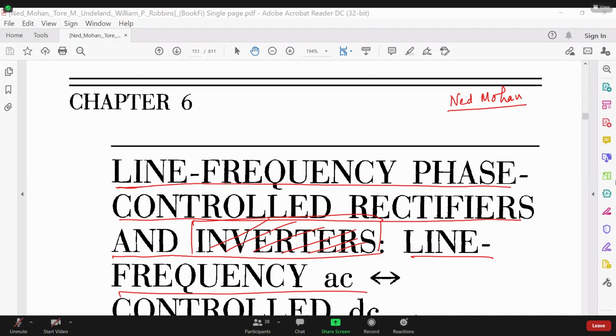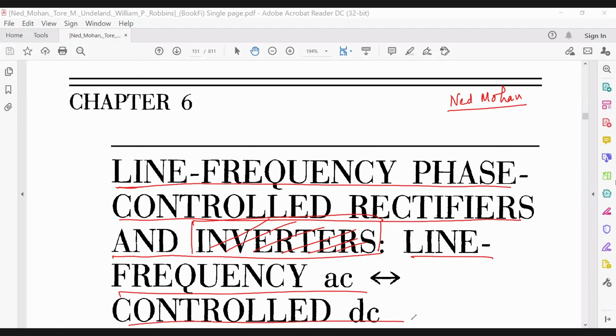So instead of just putting the brake, if you push your brake, that will not go to your wheel and waste the energy in the form of heat. Rather, you can always charge the battery. So then your energy will be fed back to the battery, and this is inverter operation. And also there is regenerative braking. It is like the same thing.